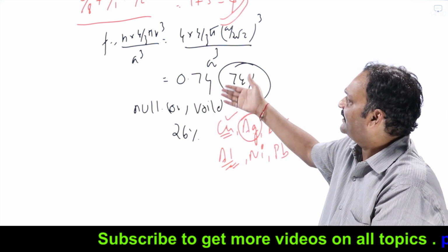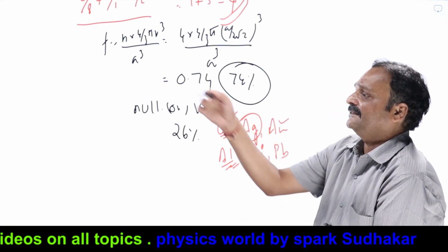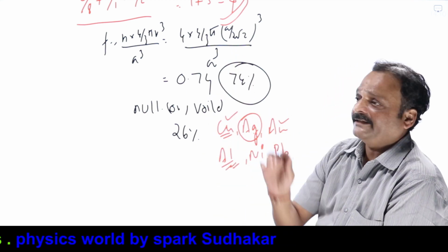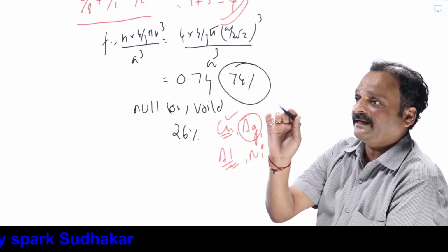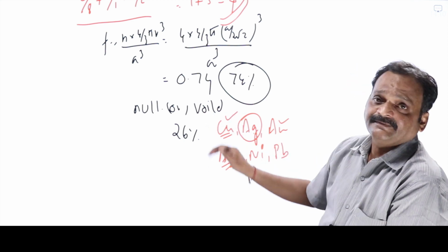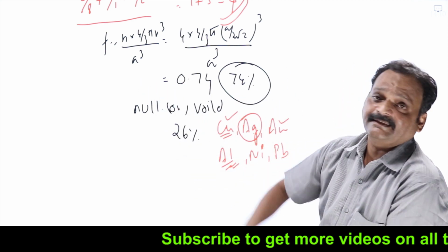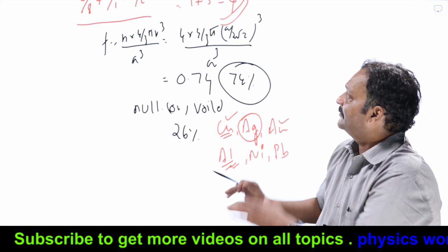You have to remember these coordination numbers. That's why in exams you get the packing fractions of SC, BCC, and FCC, all 3 in one question: 0.52, 0.68, 0.74, or pi by 6, root 3 pi by 8, something like that. For this expression, they'll give you 3 questions directly, or void spaces in SC, BCC, FCC. All put together will be coming.